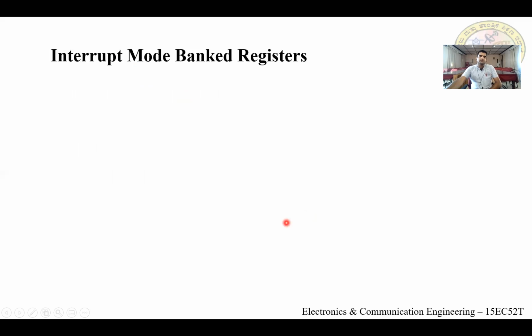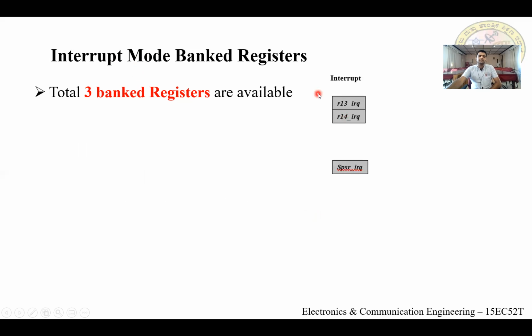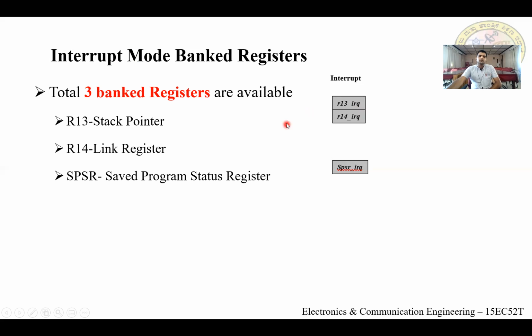Next, interrupt mode banked registers. In interrupt mode, there are 3 banked registers available. The mnemonic for this mode is underscore IRQ. R13 is the stack pointer, R14 is the link register, and next we have SPSR, the saved program status register.